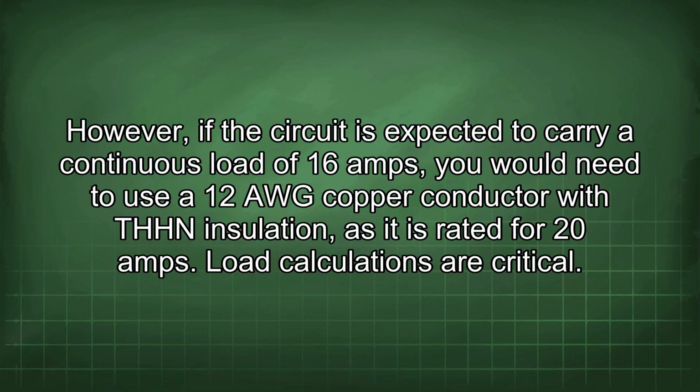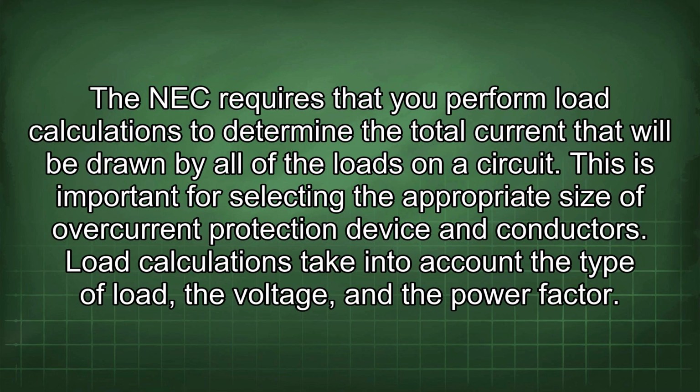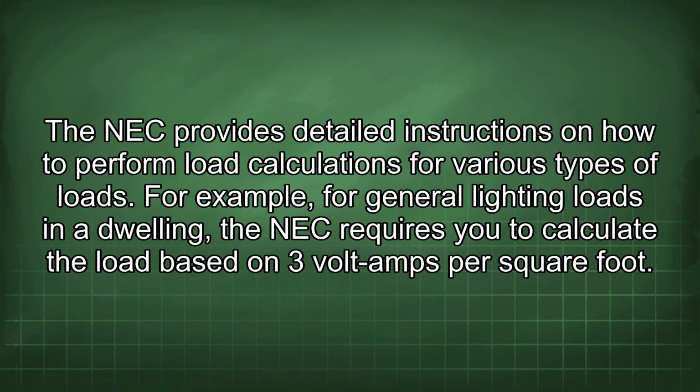Load calculations are critical. The NEC requires that you perform load calculations to determine the total current that will be drawn by all of the loads on a circuit. This is important for selecting the appropriate size of overcurrent protection device and conductors. Load calculations take into account the type of load, the voltage, and the power factor. The NEC provides detailed instructions on how to perform load calculations for various types of loads.